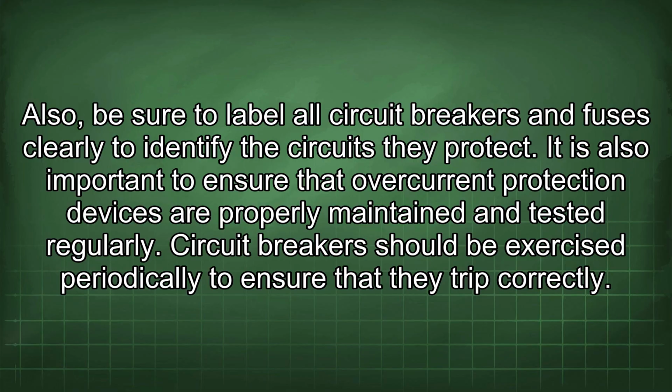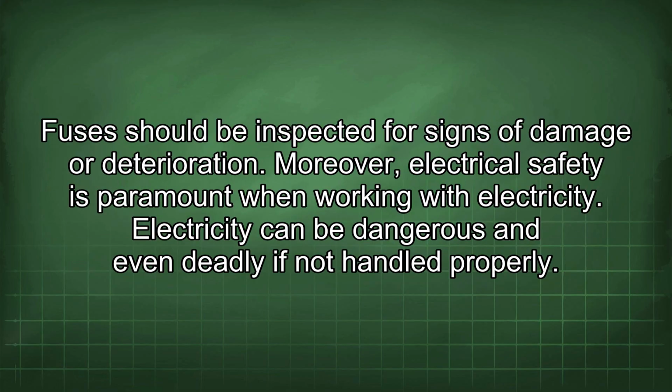It is also important to ensure that overcurrent protection devices are properly maintained and tested regularly. Circuit breakers should be exercised periodically to ensure that they trip correctly. Fuses should be inspected for signs of damage or deterioration.